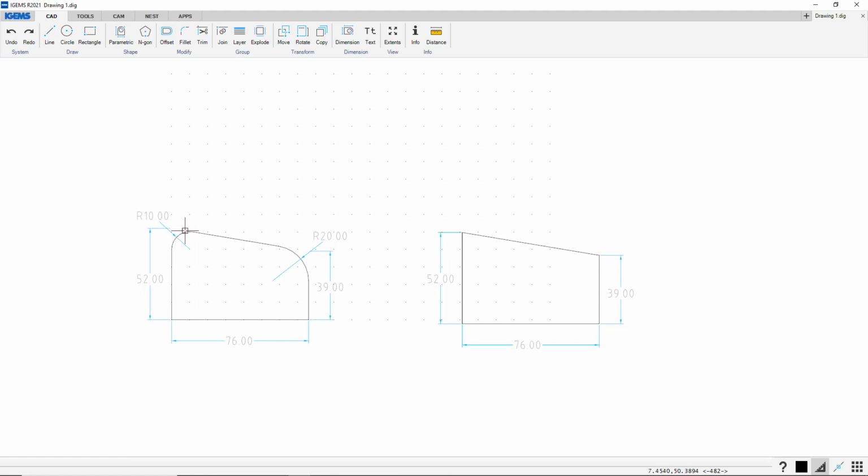and now we want to have this rounded corners, which is called fillet, with a radius of 10. So I go to fillet, short key F, and I clicked on it and it says fillet. Now we have to specify the radius, and we just type our radius, so 10. Okay. And we select the lines which we're gonna connect with a fillet.